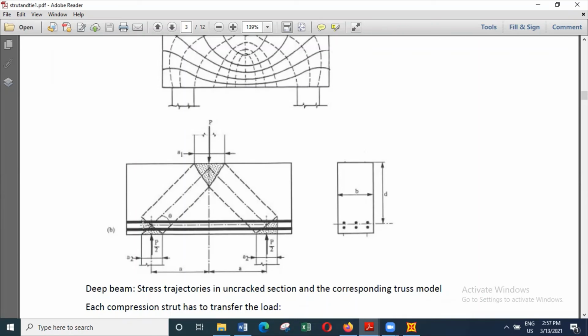Whereas if you look at this particular joint, here you can see you get compression. This way also you get compression, whereas you get tension in the steel. So this can lead to a certain amount of cracking in concrete, because we have one force in tension. Because of that reason, the force carrying capacity of this type of place will be lower.